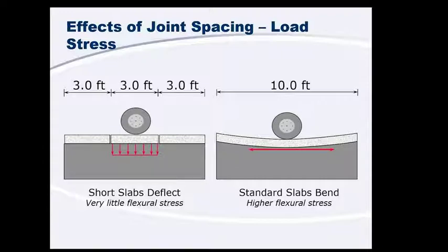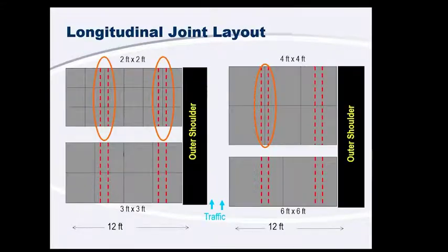One of the ways we're having a thinner section is by utilizing that support layer as part of our pavement. It helps reduce the stresses within our slab. So you might think, why shouldn't I go shorter and shorter with my joints? Well, a big reason you wouldn't want to do that is because of the location of the joint within your wheel path. Now, that can be a major issue if you have your truck traffic driving right on your joints all the time. You're probably not going to get very good long-term joint performance.